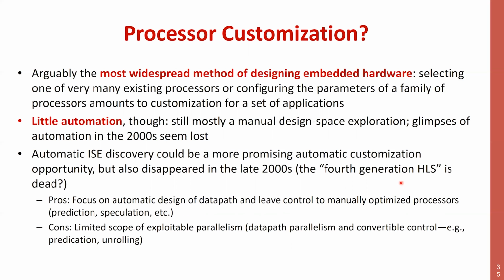Some people will come back to this later on, but some people call this the fourth generation of HLS, because in a sense, this is a form of HLS, high-level synthesis. I synthesize a system by putting there a processor. I start from code, and I generate some hardware by putting there a processor, and by deciding what I shall put around this processor in such a way that it has the highest possible performance given a relatively restricted budget of transistors and power.